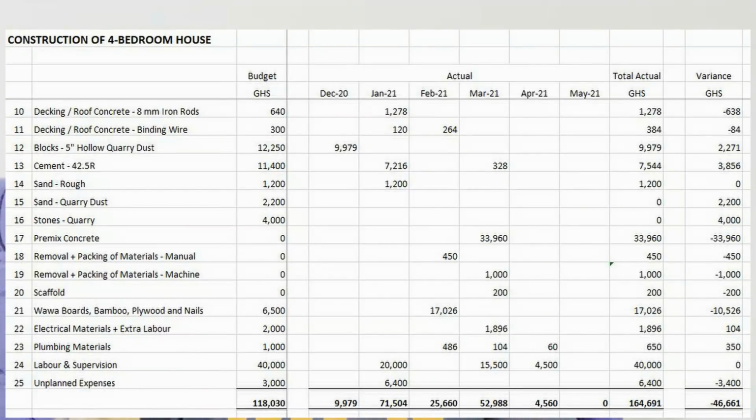Now, as I said already, it is important to have your budget estimate from the BOQ initially for each stage on your Excel spreadsheet, with your materials and your estimated labor, and then track it on a monthly basis. If say stage C is going to take you two or three months, track it monthly. This is what I've spent in January, February, March, and therefore this is my actual expenditure at the end of stage C. Compare that to your budget, and then you know whether you're in credit or in debt.